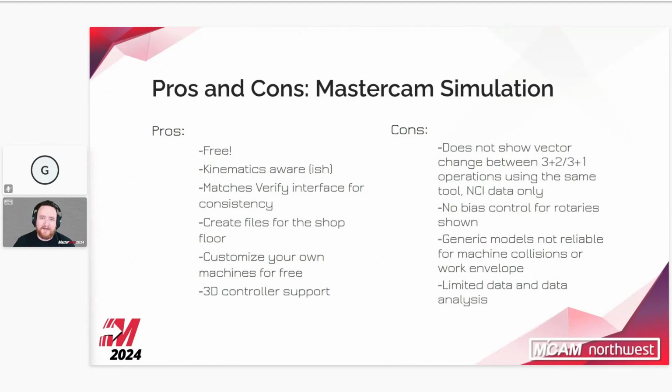Additionally, when Mastercam is installed with this, there are a handful of generic models that have general machine kinematic setups, but the actual physical space of these machines and their size is not necessarily going to match your machine. So that could be a big problem in terms of work envelope or collisions. Generally, it's also a little bit limited in its full data and analytics compared to some other options.